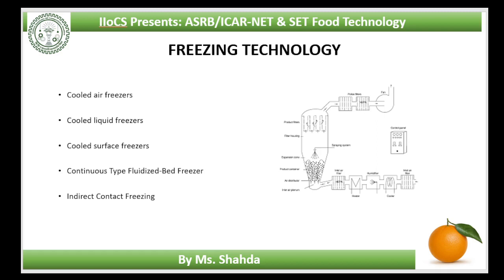No primary refrigerant is required to cool this medium, since low temperature results from the evaporation of liquid nitrogen. Liquid nitrogen is non-toxic to food constituents. Moreover, it can displace air from food and thus minimize oxidative changes during freezing and throughout packaged storage. High quality frozen foods are produced because of the high speed of liquid nitrogen freezing. High cost of liquid nitrogen remains its major limitation.